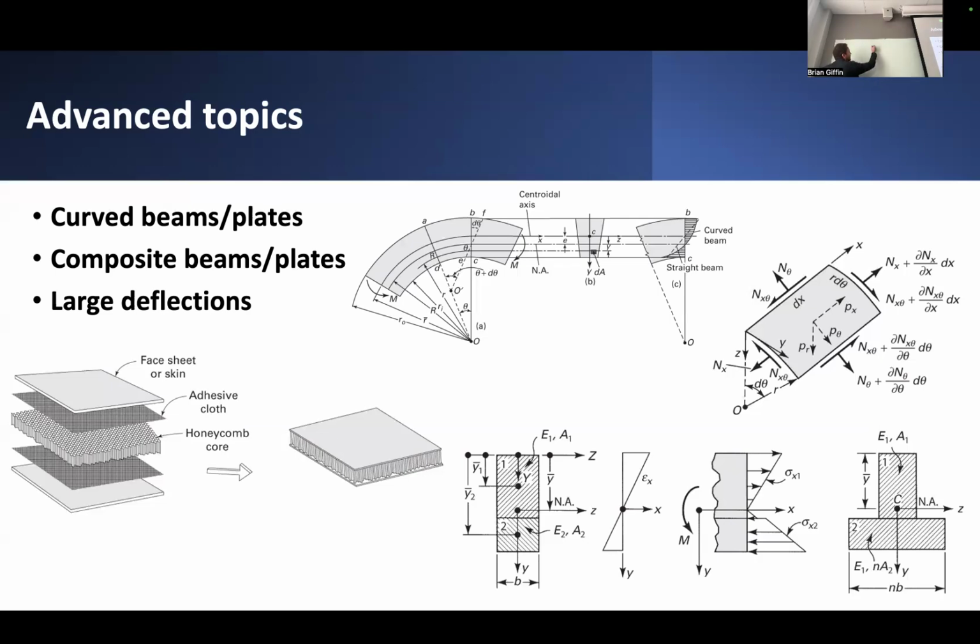So if I had, let's say, this sandwich panel, and I wanted to know what's the actual section deformation. If I assumed it was strictly linear, or that this plane section remains planar, then it would look like this, but maybe it would actually look something more like this. Let's suppose that this inner core material is relatively soft, such that it allows a lot of relative shearing deformations to occur.